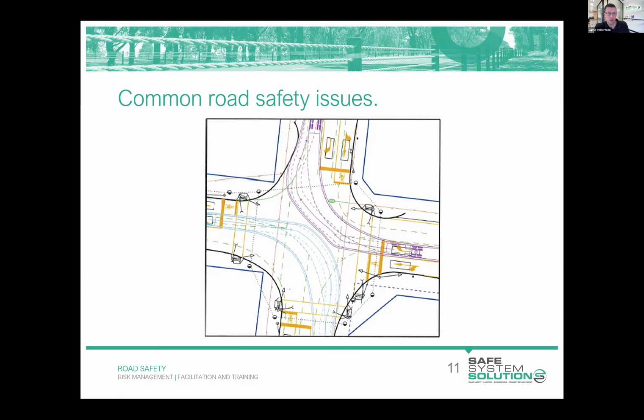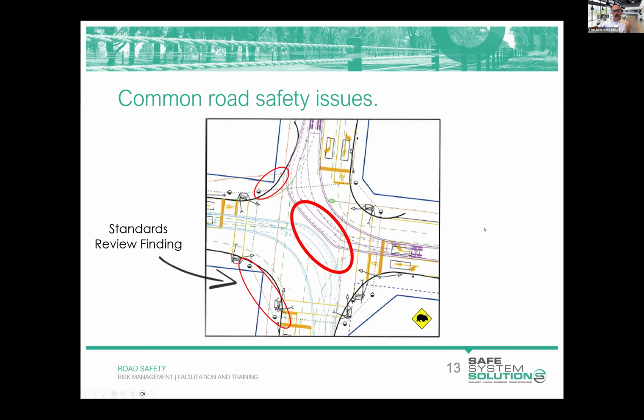Are there any questions around that swept path diagram? So that's, I would say, a poor example of one, and it sort of reeks of back to front design. It's clearly a constrained location. An intersection appears to have been designed that fits within the property boundaries, and then some swept paths have been put down on the top. Whereas the desirable process would be to construct your swept paths in a desirable way and then design your intersection around those. We jump on to your next slide there with some annotations on that, Jamie.